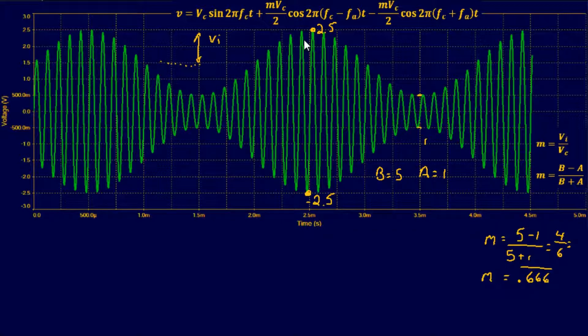Okay. Now you got to do the same thing for your voltage for your carrier. Now the voltage for your carrier would be this point, 0 to the 1.5. So it would be from here to here. That's VC. So that'd be the very center of your AM waveform to the center of your envelope. That's the easy way to do it. If you can find the center of where your envelope is, from there all the way to 0, that's your voltage for your carrier.